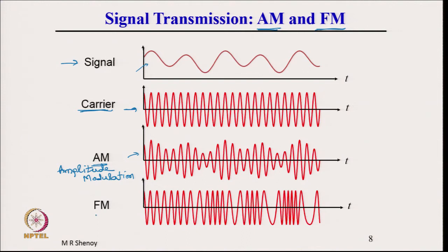In the second case, frequency modulation. So, this is frequency modulation. FM is frequency modulation. Many of you will be aware of these things. In frequency modulation, the carrier has a certain constant frequency, let us say Fc or F0. And what we see here is that the frequency in some places is more, F0 plus, and here we can see that it is F0 minus.